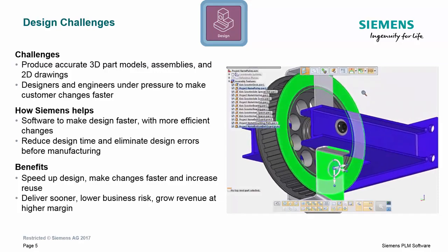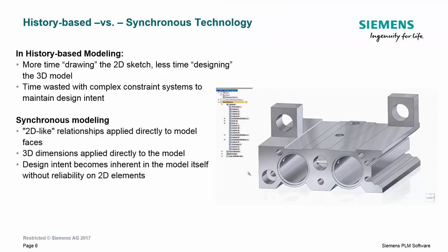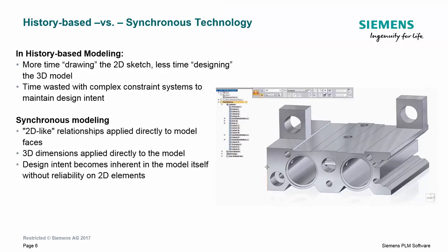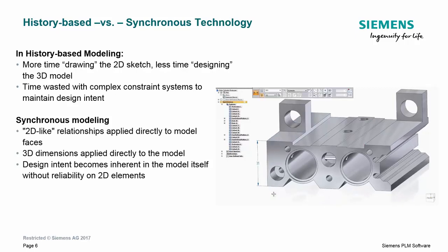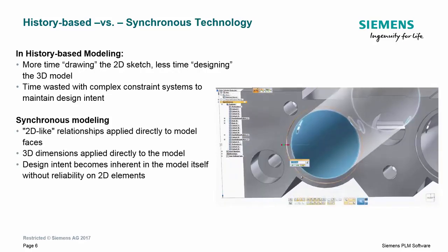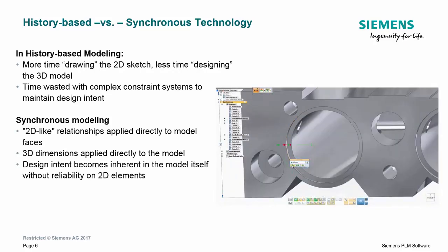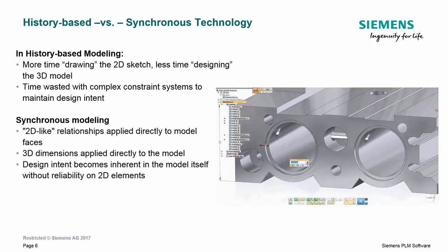of their customers. As mentioned earlier, history-based is the most prevalent and well-known modeling method on the market today. With this, it has become commonplace to spend a lot of time and care constructing and constraining complex sketches in order to preserve the intent of a particular design, not only for Solid Edge ordered users, but designers using any other history-based CAD system as seen earlier. However, Solid Edge synchronous technology allows designers to freely make changes to design intent using the 3D model faces themselves, allowing for intuitive changes to designs.